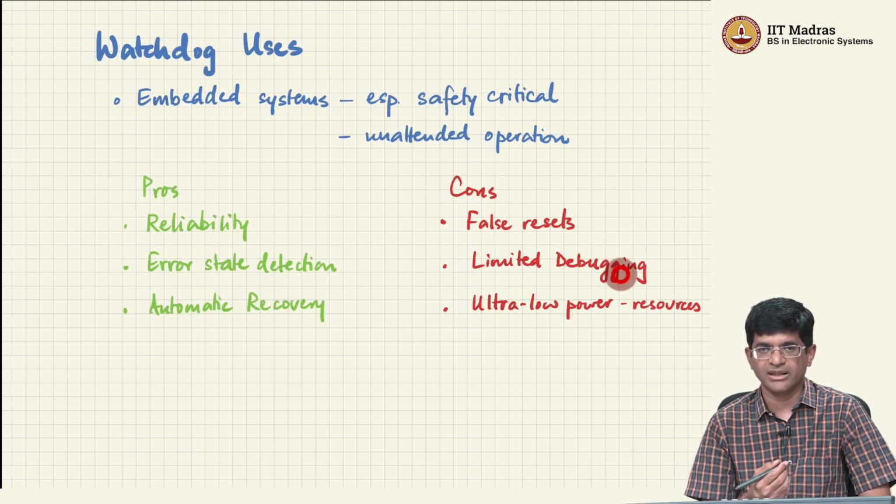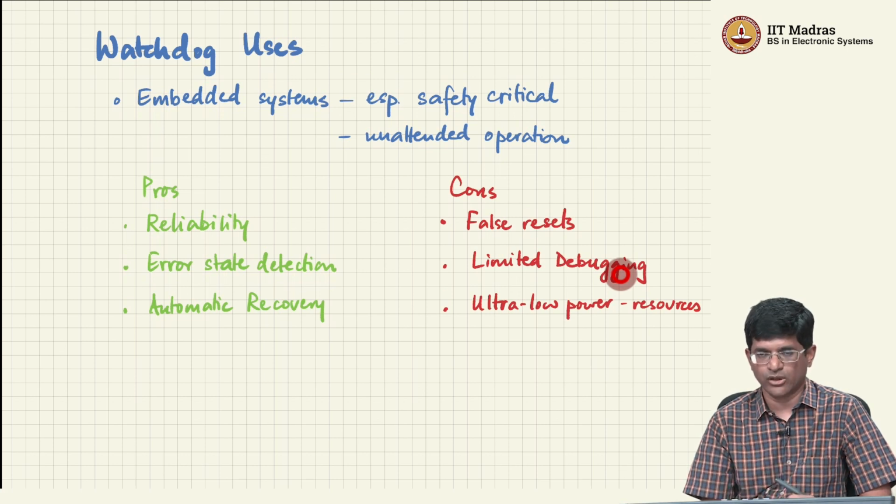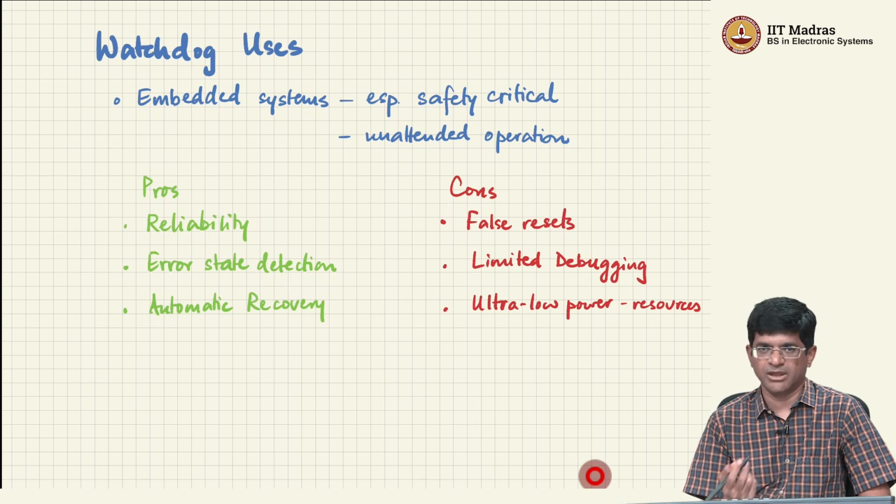And in fact, unfortunately, the CPU itself was hanging, it was stuck. So it's quite possible there was no way to get that information of what went wrong, but it does limit your debugging capabilities. And in certain kinds of applications, especially ultra low power systems, just having a watchdog itself can be a problem, because that's another source of power draw, right? But obviously it's a trade-off, right? Like everything else in engineering design, you need to decide whether the benefits of having the watchdog outweigh the drawbacks that it gives you.